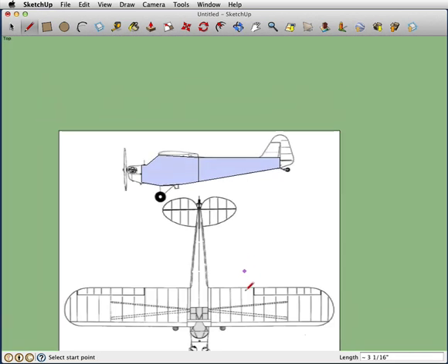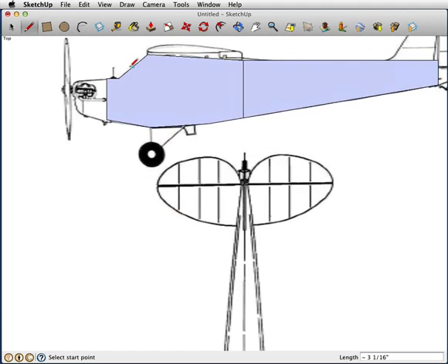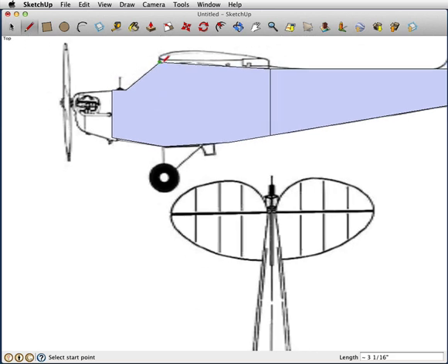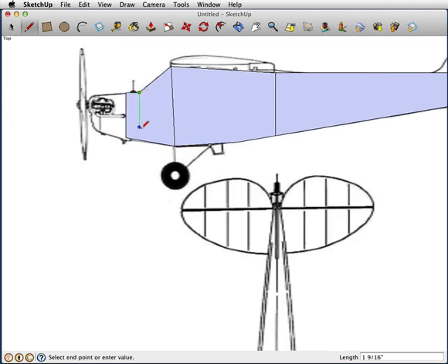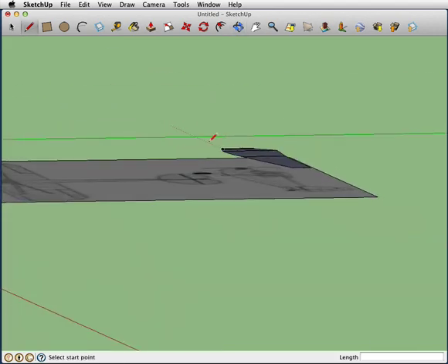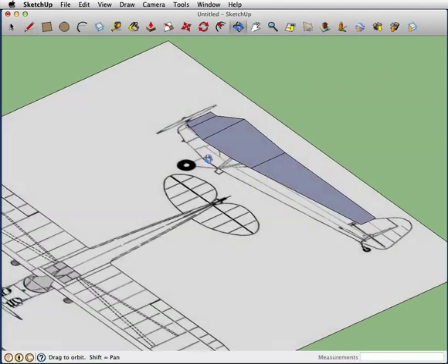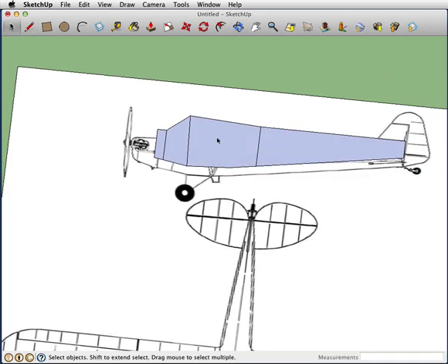And then looking up front, it's relatively straight on for the most part. Let's go up here, and I'm just going to bring this one down to here. And I think I may just bring this straight down to there, so that now we've got some panels that we can sort of fold inward. All right, and right now they're still just completely flat if I rotate around. Oh, and I also notice that my faces are reversed, so let me triple click and reverse faces, so we've got the white side facing up.